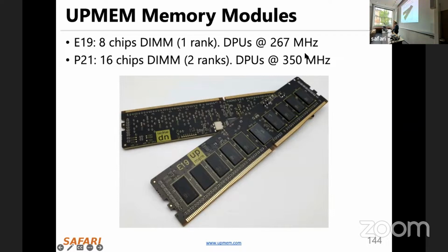They operate at very low frequencies. And the reason is they're implementing this on a DRAM process. And DRAM process is really optimized for a different fabrication goal. So everything is different in fabricating DRAM compared to CPU logic. It's really optimized for the capacitor. You need to really make the capacitor small, etc. And as a result, if you want to put logic in it, and if you want to operate at very high frequencies, this becomes extremely leaky. Or you need to actually put a lot of huge buffers, etc. So they operate at only 350 megahertz. The comparison point is 4 gigahertz or so for CPUs today, right? So immediately you're bottlenecked by frequency, as you can see, near the memory side. But even then, you can get some benefits.